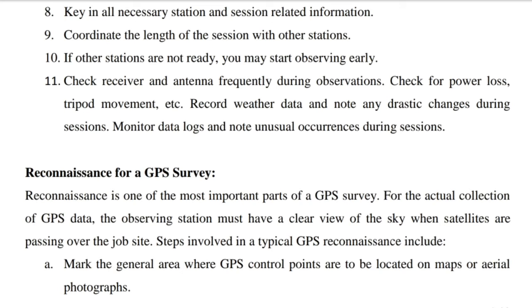Reconnaissance for a GPS survey. Reconnaissance is one of the most important parts of a GPS survey. For the actual collection of GPS data, the observing station must have a clear view of the sky when satellites are passing over the job site.